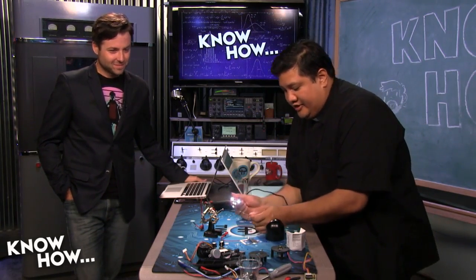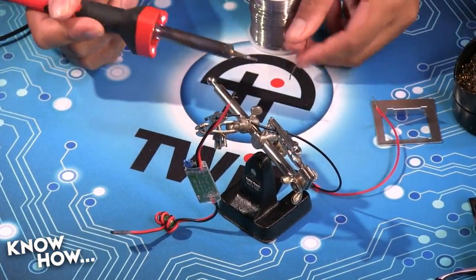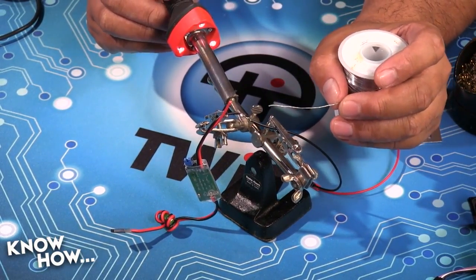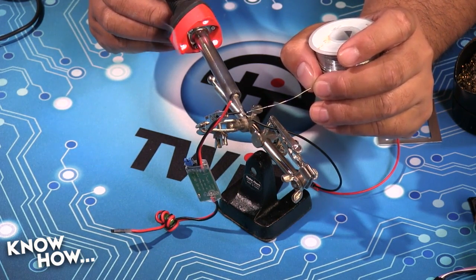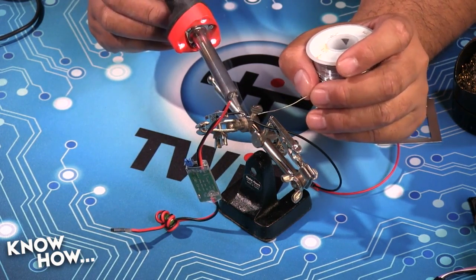So a little bit of solder on the tip of my iron sort of gets things going. It also cleans off all the crud that's accumulated. Remember, whenever you're soldering, and it's always good to repeat the beginner tips, you're not heating up the solder. You're heating up the wire. You want the wire to be able to carry the solder, because then the solder will flow over the wire and make a better connection.